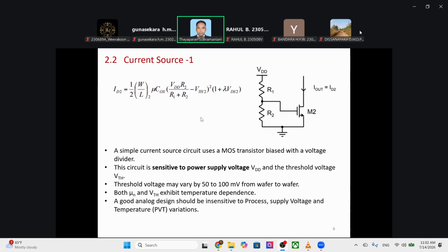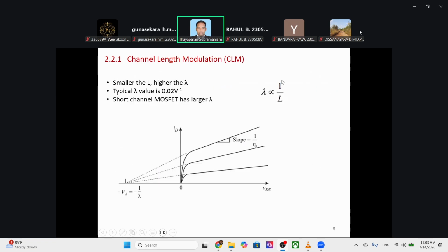Right? It's a constant. Once you set this constant, then the current is constant. If we don't have this one, but what it introduces is a linear variation in the ID2 if we increase the drain source voltage. So if you look at the characteristic waveform, it will be like this, slope exaggerated. Most of the time it will be flat. It should be flat.